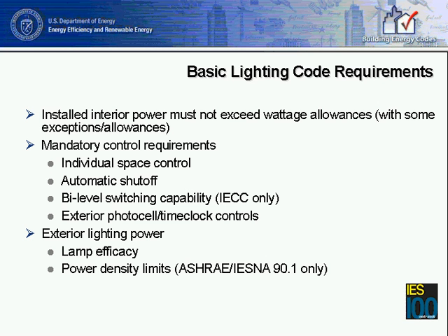And they start with the major one, which is installed interior lighting power. The requirement is that whatever lighting power goes into the building must not exceed the allowed wattage based on the code requirements. And there are, of course, some exceptions and allowances to that.